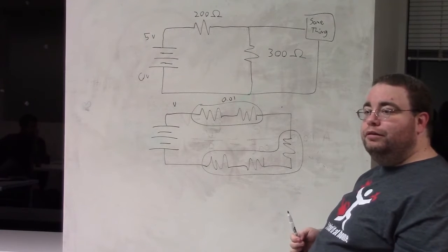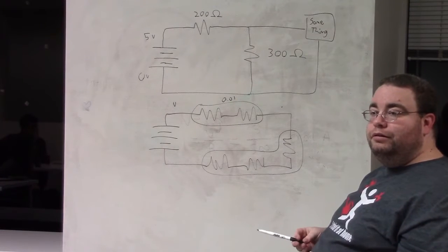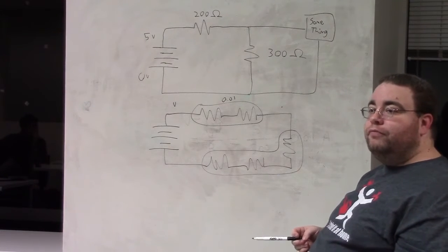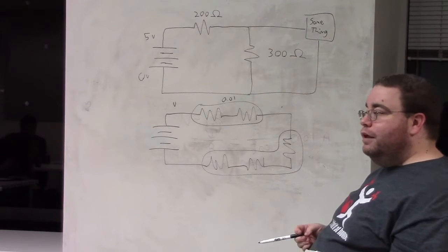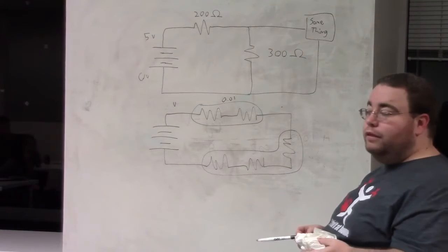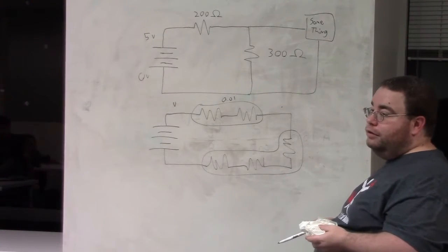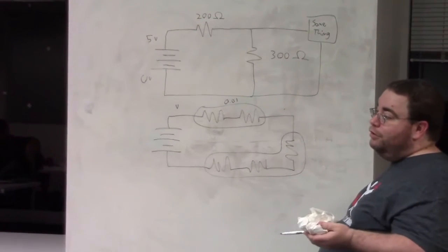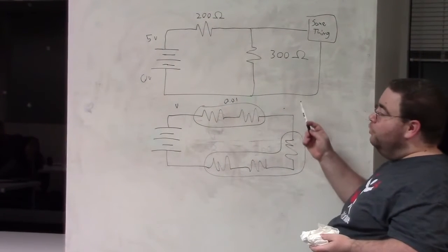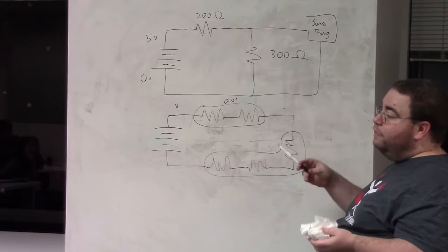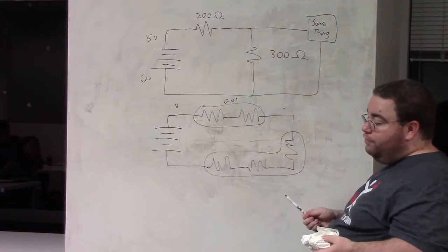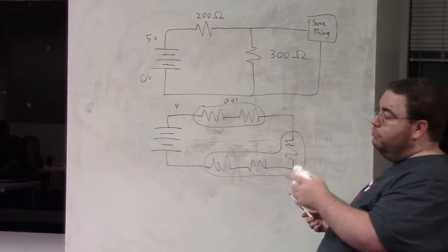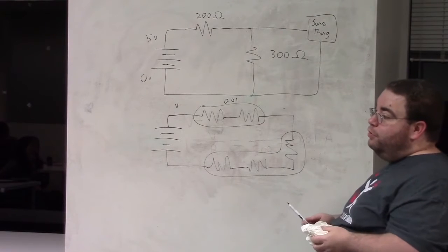It compensates for your loss at the end versus what you need, so it pumps more current to keep that voltage. It's just a more efficient way of getting there, because there's more circuitry in it to regulate. On the other hand, it's a bigger, more expensive part. So whenever you can use a voltage divider for something that's not going to use a lot of current, then it's probably better. The other way to drop to 3 volts, there's a part called a Zener